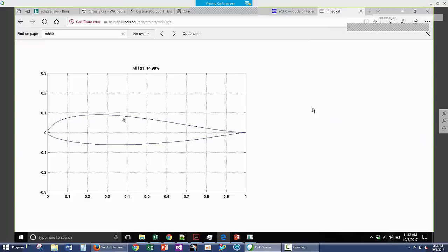One of the parameters that we care about in selecting the airfoil is the thickness to chord ratio. If you have a higher thickness to chord, everything else being equal, it's better because you have more physical room for structure. And if you recall from beam bending analysis, you're going to get a bigger moment of inertia if you can have a spar that is thicker. So for the exact same amount of material, you can overall get a stronger and stiffer wing.